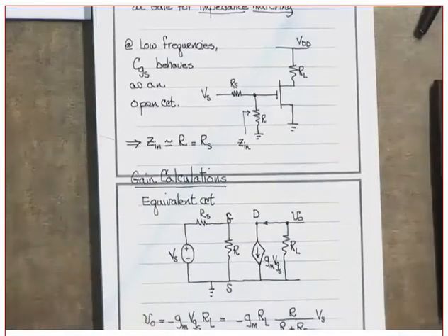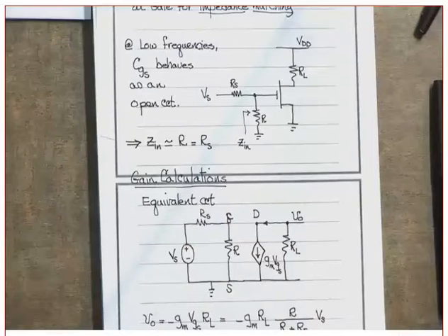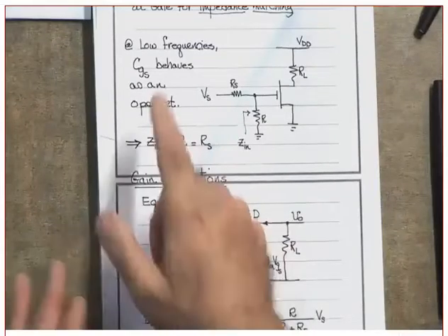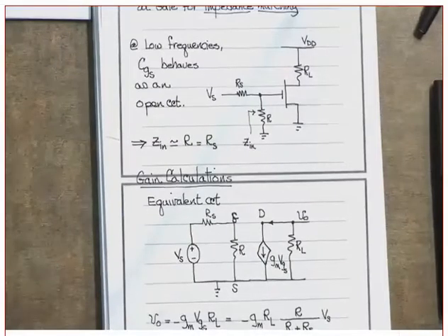And if the input impedance is a capacitive impedance, there is no way that I can match it to a real resistance. A real resistance being the 50 ohm coming from the source. Clear? Either from the feeder cable or from a filter in there.